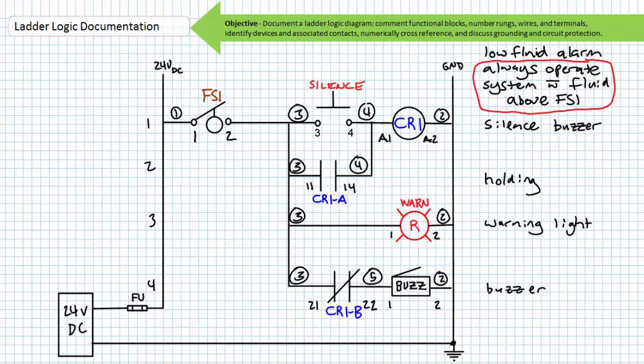The schematic is drawn such that gravity would ordinarily pull the switch closed. However, it's being actuated into its activated open state by being immersed in liquid. It's for this reason that I ordinarily use the arrow convention that makes it explicit and obvious the normally closed float switch is being actuated into its activated open state.